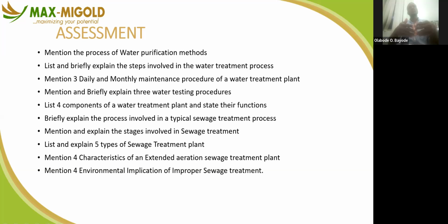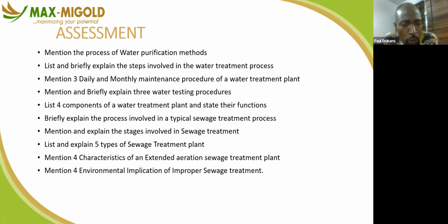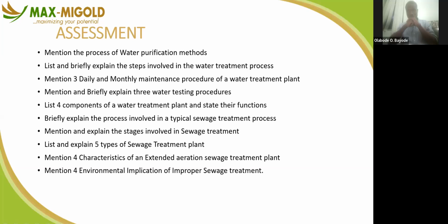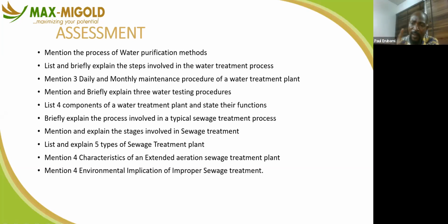What I will advise you to do is excavate the manhole and do a very fresh one. Then the first surface of the manhole, what you apply is what you call water cement. The reason why you are having that issue is that if you apply normal cement, there shouldn't be any water going into the manhole for at least a minimum of 24 to 48 hours, because you need to allow that cement to cure. But if you apply cement and in less than 2 hours you start having water flowing to that place, it will wash off all the cement completely.